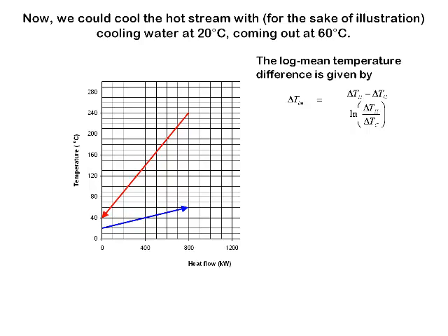Now the size of the heat exchanger that we would need depends on the size of the temperature driving force causing heat transfer to occur. If we assume a pure countercurrent heat exchanger, then the temperature driving force is given by the log mean temperature difference, and that's described by this equation. Delta T log mean equals the temperature difference at the hot end of the heat exchanger minus the temperature difference at the cold end of the heat exchanger divided by the log of the ratio of these two things.